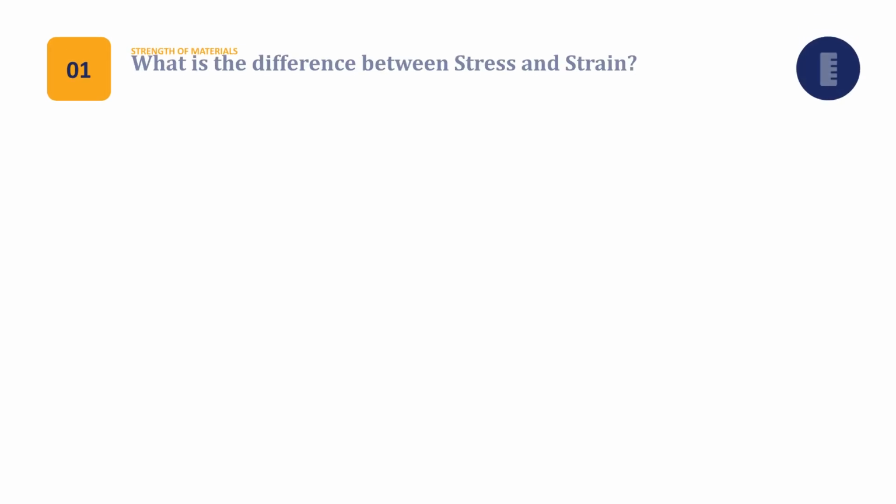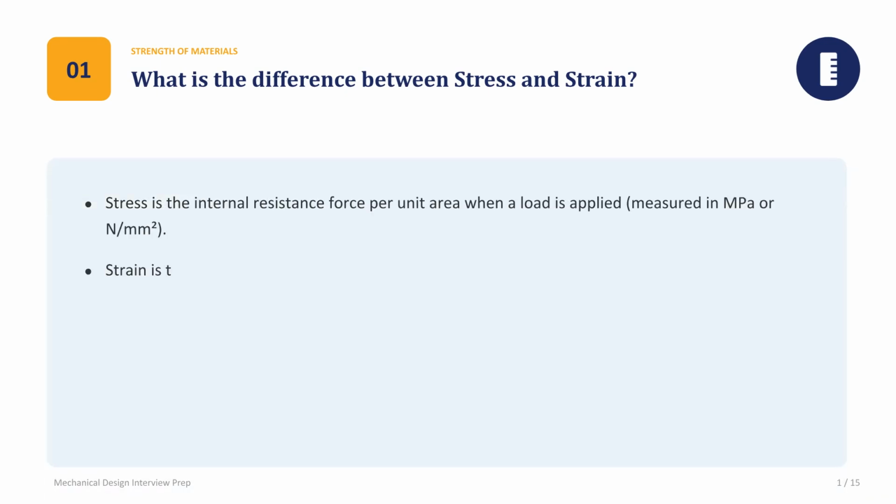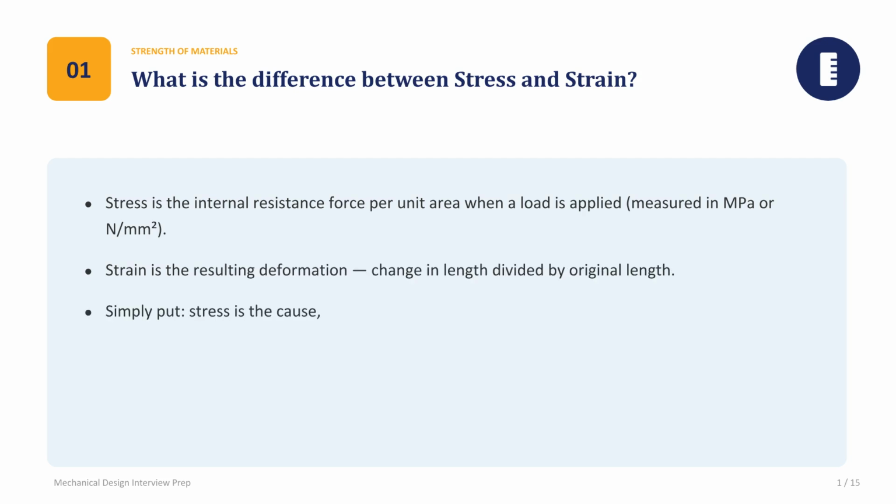Question 1. What's the difference between stress and strain? Stress is the cause, strain is the effect. Stress is the internal resisting force per unit area when a load is applied, measured in megapascals. Strain is the resulting deformation, change in length over original length. Cause and effect.